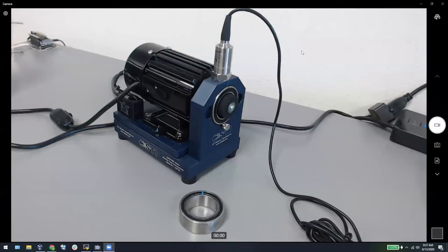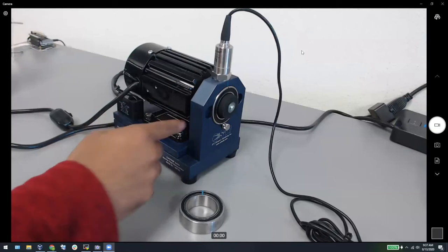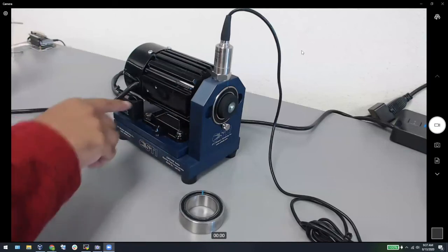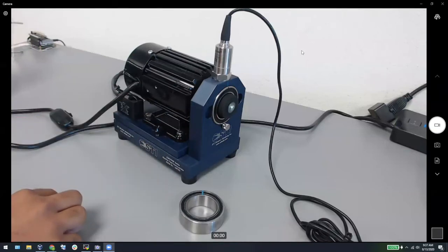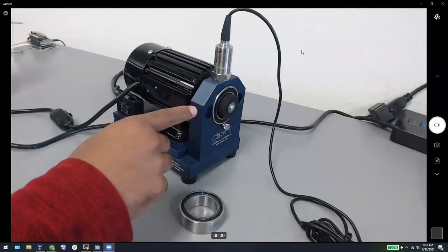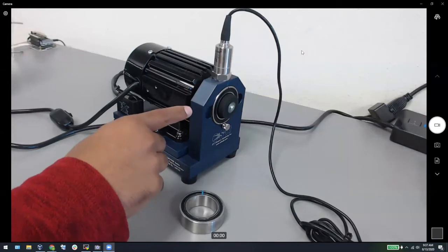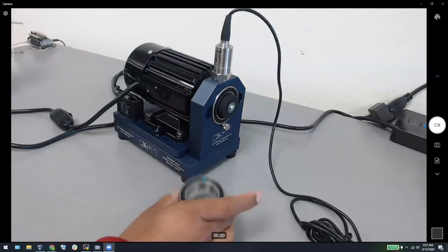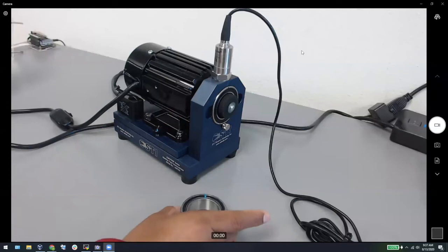Hi, everyone. So this is our vibration demo. I'm Ashwin Gopalakrishnan from Dianomic Systems. What we're running here is a vibration demo in which we have this motor setup. It's basically a tabletop setup of a motor. It's representative of something that you might see in an industrial setting where they have pumps and other pieces of rotating machinery that they want to monitor. Now, this particular motor is currently engaged with one of two bearings. This is a good bearing that's engaged. And what I have here is a bad bearing, one that is known to have an inner race fault, a common problem in these types of settings.